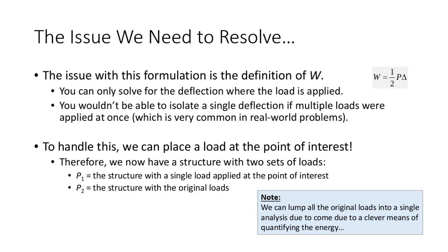I have one with the structure with the original loads, which I'm actually calling P2, and then P1 is the structure with just a single load applied where I'm trying to find the deflection. So if I have a structure and I wanted to find the deflection right there, I'm going to put the load right there. And when I say the load, we'll talk about what that means here in a second.